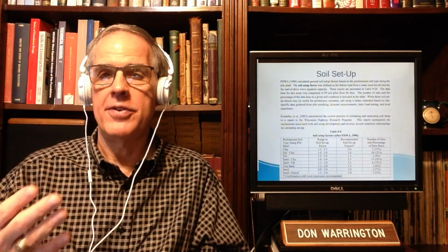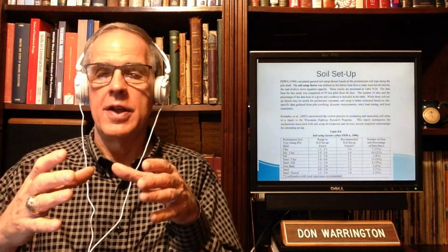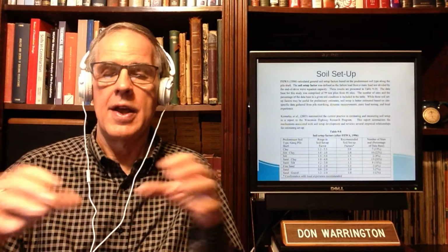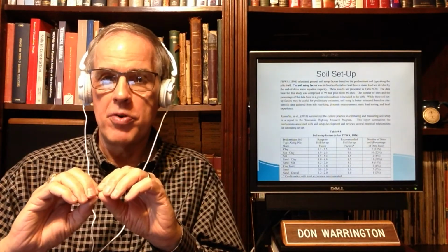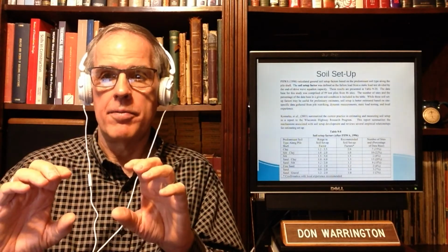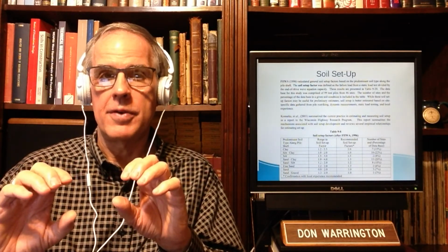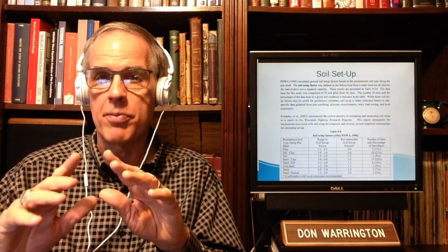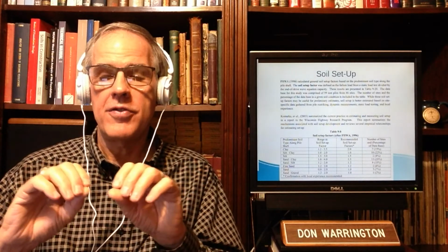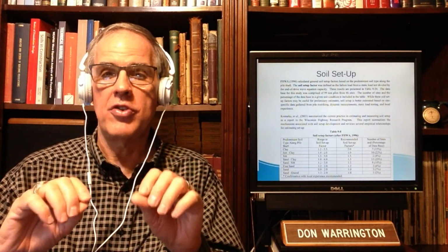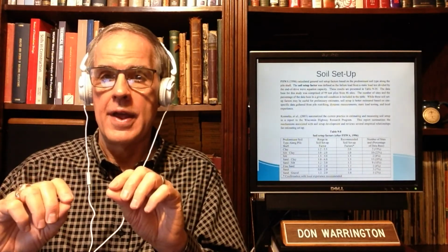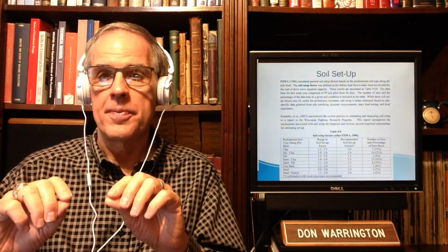Therefore, the pressure of the fluid has been raised. That fluid pressure is pushing the particles apart. The fluid pressure between the pores acts on the particles and pushes them apart. And what that does, if you remember, is reduce the effective stress of the soil around the pile.